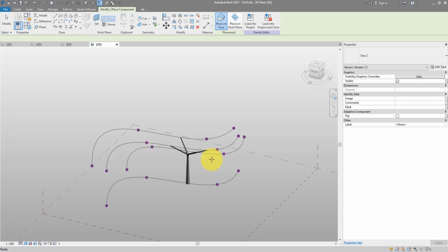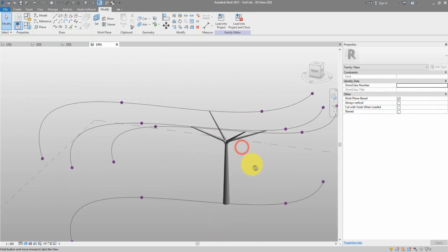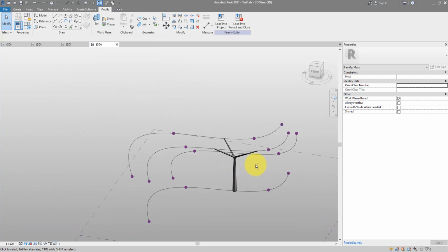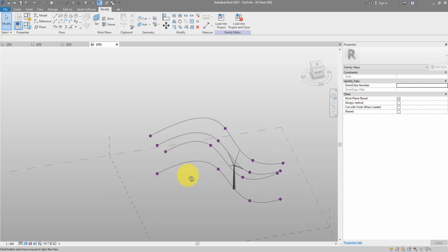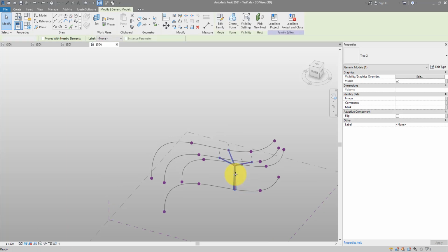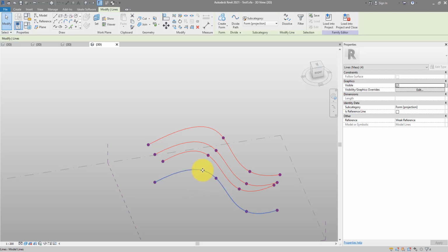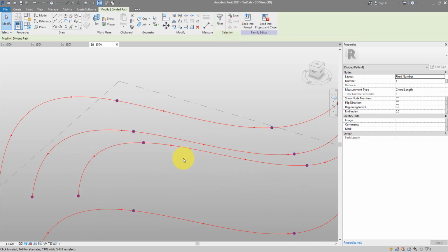You see now it's getting better. No longer funny branches pointing to the ground. That's our tree family there. So if you want to just place them one by one like this, those trees are ready. But how about we try to make sure we can just array one tree quickly along the same path to make the whole system into a quick and easy promenade that you can create in seconds. Let's try that now. I can remove this one first and turn those 4 curves into divided paths. Just get them like this and click on this divide path button there. Now you see they have divided points along their lines.